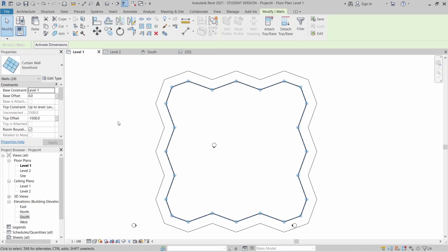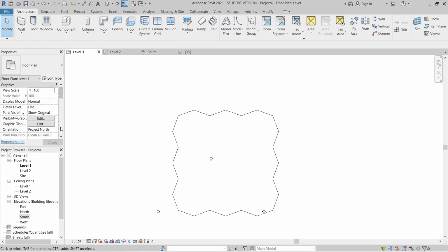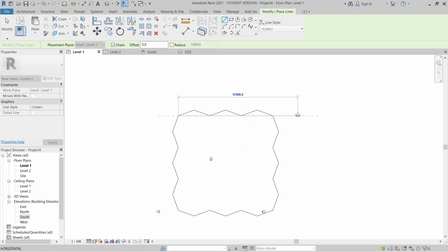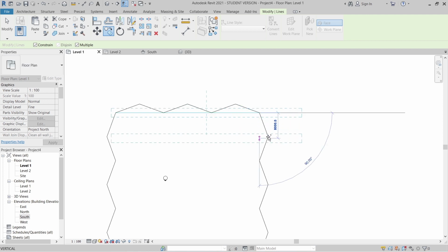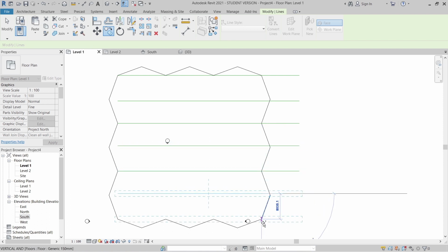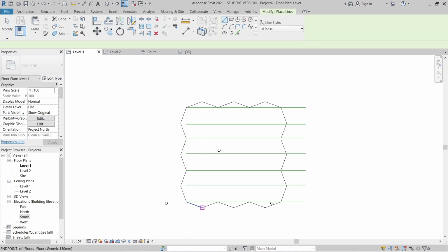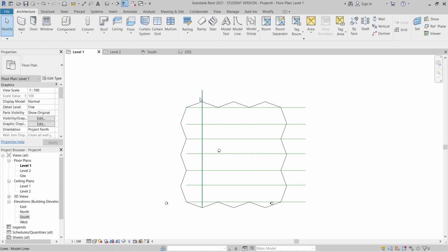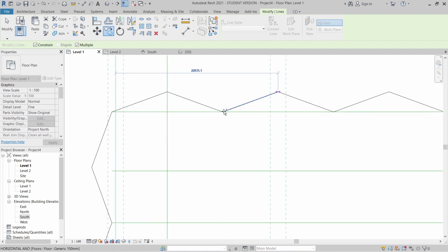Let me hide our glass first. We hide for high element. Then now it's time to create our grid line. I will make it faster. Scan LI for shortcut key. Simply draw here. Again, I need to copy that. Okay, then again here for another vertical one. Make sure you turn on multiple selection.